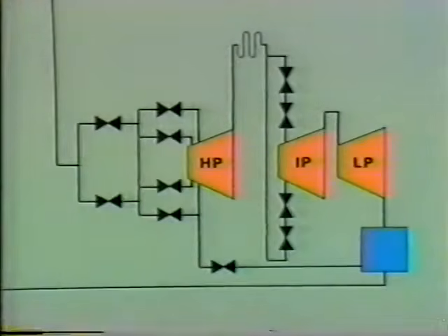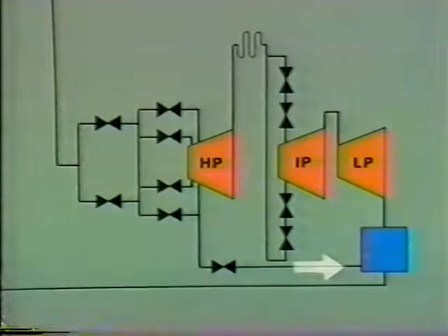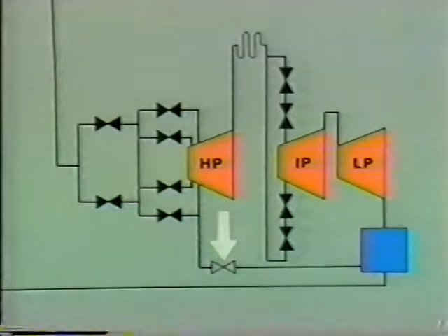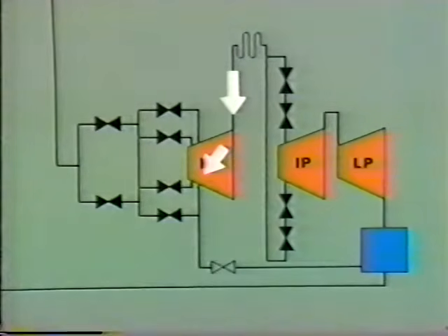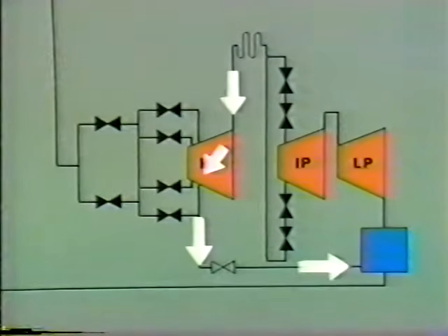The ventilator valve is connected to a steam line between one of the control valves and the HP turbine. The ventilator valve discharges directly to a low-pressure area, normally the condenser. When the turbine trips, the ventilator valve opens. When it opens, a small amount of steam is drawn from the reheater through the rotating turbine blades, through the ventilator valve itself, and then the steam is exhausted to the condenser. This flow of steam prevents heat from building up in the HP turbine.